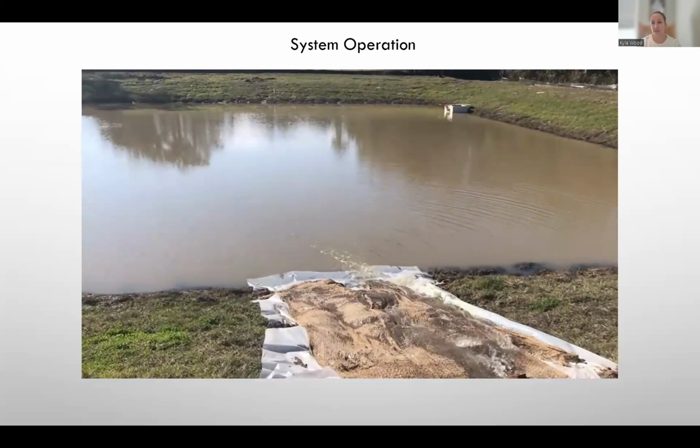It's not hazardous. So a lot of times when we have saturated jute matting that has all this flocculated sediment with the polymer, we like to tell people to take those and use those for erosion control on other areas of your site. If you clean out a basin, now you have this polymer treated sediment. Use it as